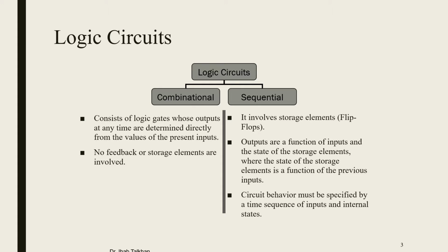But now I'm going to talk about sequential. Sequential means, as you saw in the video uploaded in the Google Classroom, that this involves loops. Loops means something related to time, because at a certain time it will give a value and at another time another value, and so on. So the sequential circuit depends on time as well as frequency, because F equals 1 over T again. As long as we are talking about dynamic changes, it involves storage elements, which means something like flip-flops.